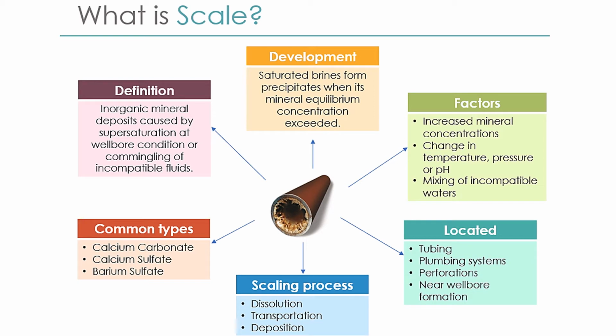scale is a form of inorganic material deposit caused by supersaturation at well-bore conditions or commingling of incompatible fluids. Scale will develop when saturated brines form precipitates when the mineral equilibrium concentration is exceeded. There are a few factors that cause scale to form, which are an increase in mineral concentration, changes in temperature, pressure, or pH of the environment, as well as incompatible waters being mixed together. Scale can build up anywhere from the reservoir up to the surface.